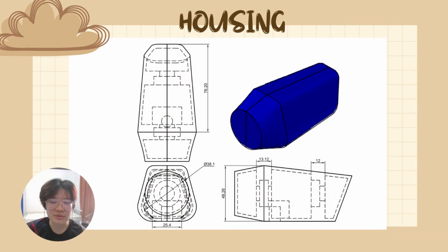So next we have moved to the other part of the drawing of the wind turbine. This is the part of the housing. As you can see in the diagram, we started constructing the main outer housing first. So we created two nearly identical planes. For the first plane, we utilized line tools to draw the wiring cover, connecting the upper and the lower parts by tangent line in case it is a circle plane, and loft command is used to connect the non-circle planes.